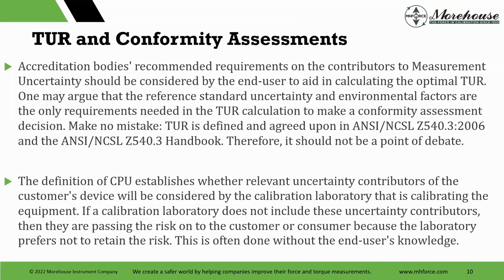But anyway, CPU is calibration process uncertainty. It establishes whether relevant uncertainty contributors to the customer's device will be considered by the calibration laboratory that is calibrating the equipment. If a calibration laboratory does not include these uncertainty contributors, then they are passing the risk to the customer or consumer because the laboratory prefers not to retain the risk. This is often done without the end user's knowledge. There is a lot of text on this slide.